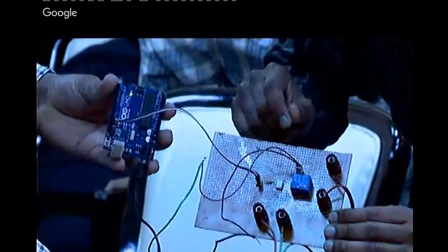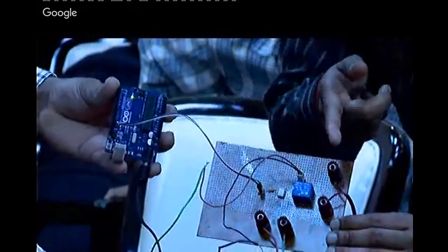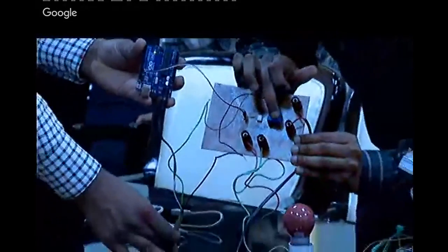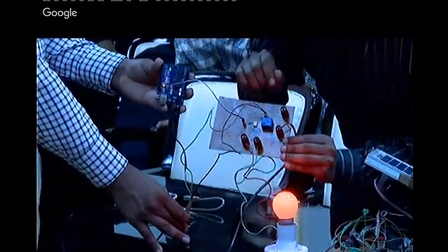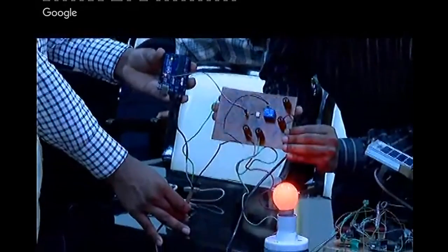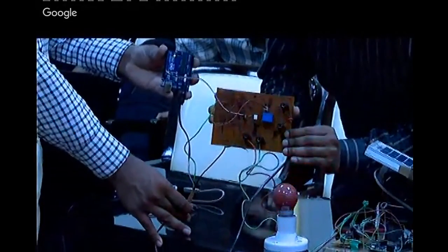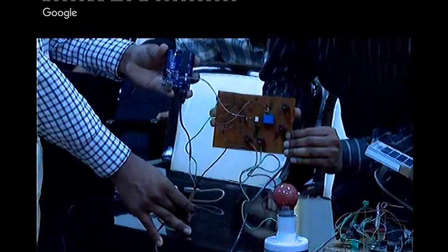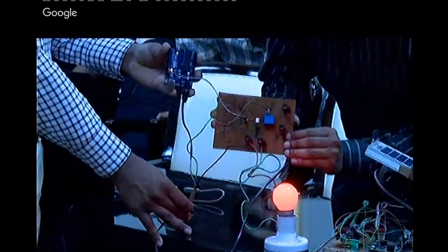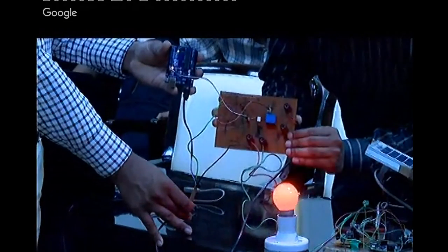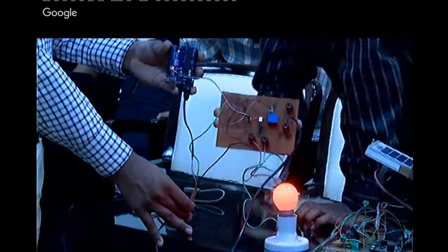When it turns on, it will turn on the relay, and the bulb is connected to the NC or NO of the relay. You can connect it with the NO or NC. It depends on your application. In the NC, the bulb is continuously on. When you give the input, it will be disconnected and it is off. With the NO, normally open, when you give the triggering voltage, it will turn on. And in this project, I have connected it with the NO.